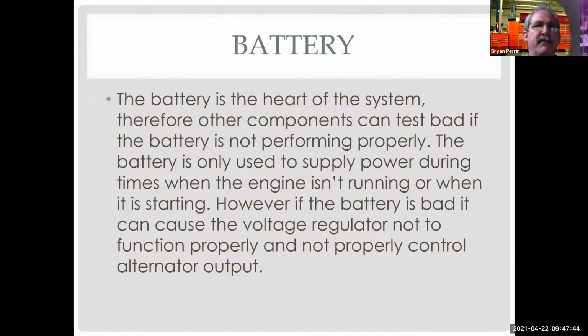Also, even if my battery voltage isn't going low, my charging system is only going to put as much in the battery as it says it wants. So what if my battery says it's not hungry? It doesn't want any amps, yet it's only 50% full or 25% full. But it keeps telling the charging system, no, I'm good. Now the charging system's not going to charge up the battery correctly, and it may not have enough current available for other loads.